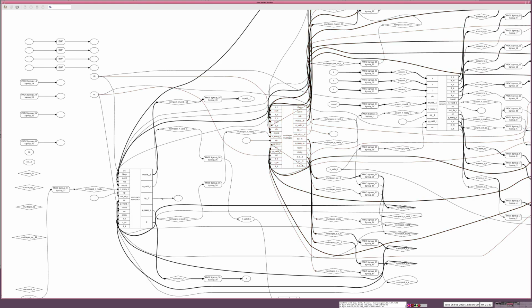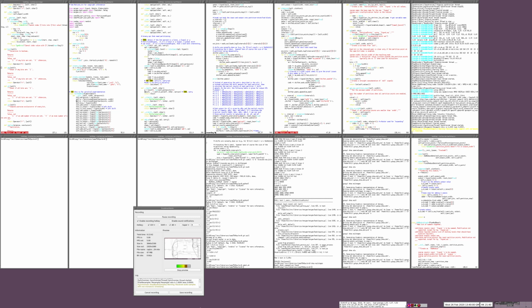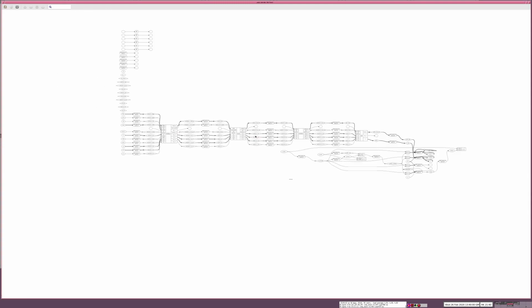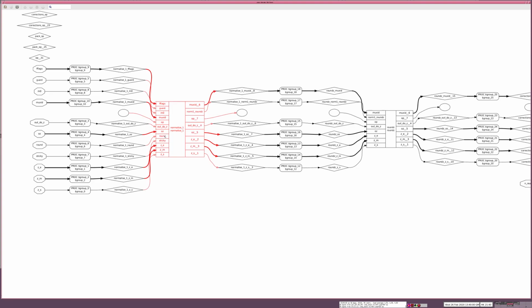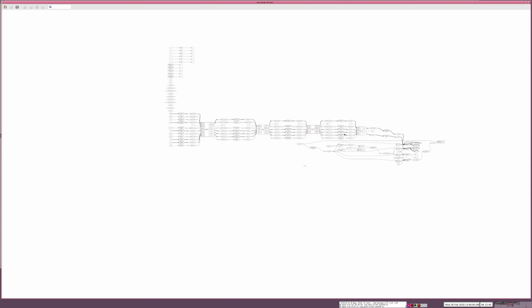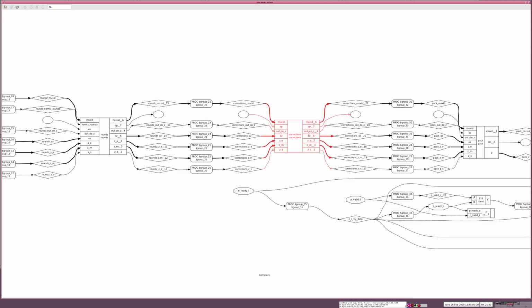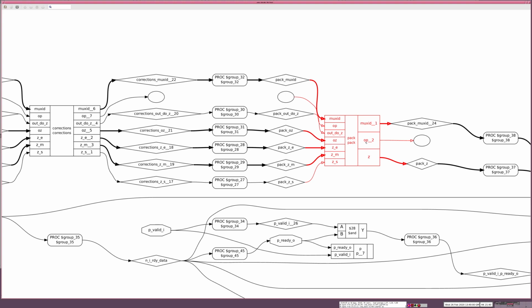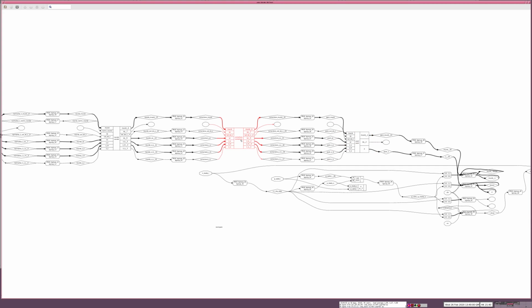So back up a level to the ALU, and finally we have the normalization and packing. So, norm and pack. Again, a chain of 4 combinatorial blocks: normalize, rounding, some corrections, and finally packing the result. And that pack is very, very simple, and could actually be a dummy or just a blank thing. If we look at normalize,